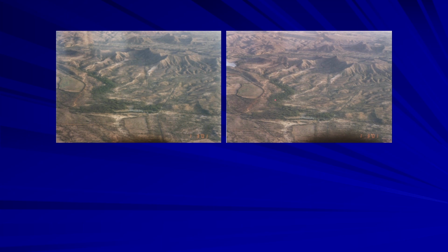Okay. So, if you have an overlap here, and this is almost a major overlap we can see, because you have this portion which has been seen here, and this hill is seen over here. So, I am having more than 70 to 80% overlap, but this was taken with the digital camera through the aircraft. But this can again help, because both photographs have been taken by the same camera, but at a different angle, that is your view angle we are talking about. So, that can again give you the 3-dimensional view of the terrain.